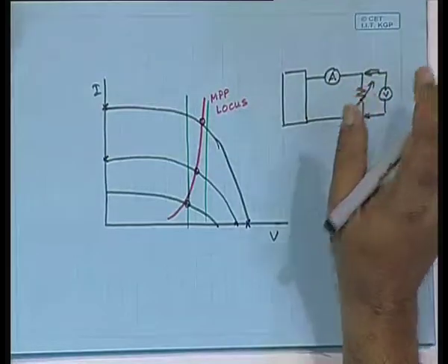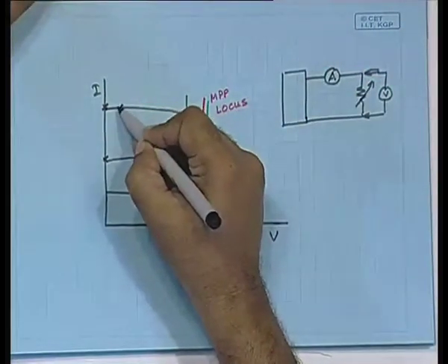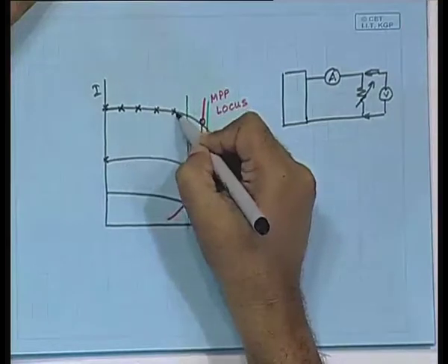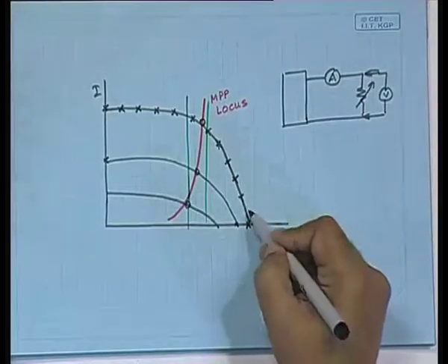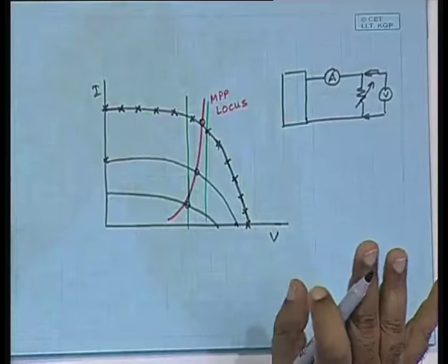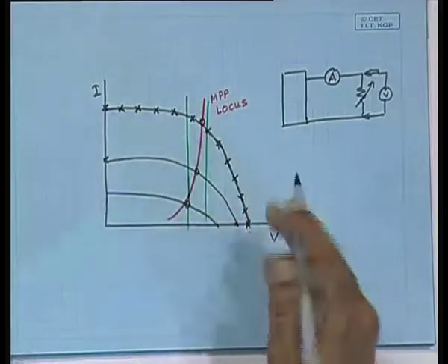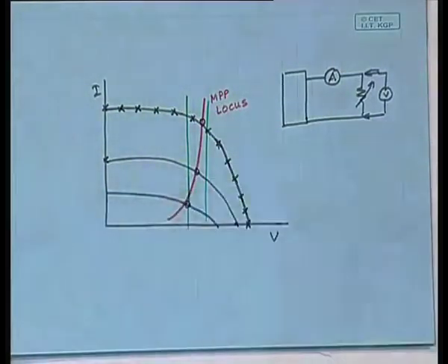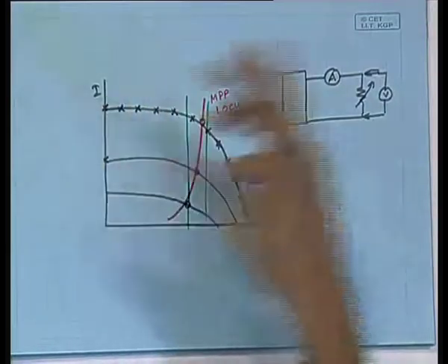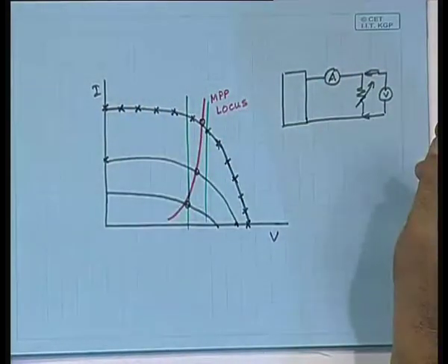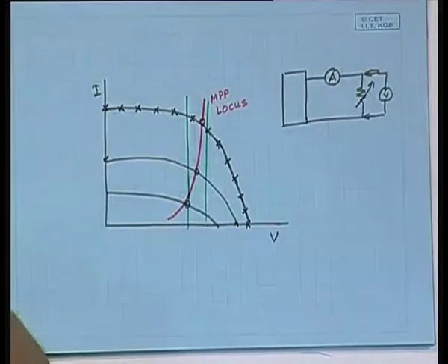Clear? And moreover, in an experiment it is normally desirable to have points located equally distant, right. You would like to do it like this. So, if you do it like this, then you know that okay, I am fine. But it is somewhat difficult to obtain equally spaced points, because what do you normally do? You normally take a rheostat and move it equally and keep on taking readings. If you do that, you will find that they are not coming equally spaced, because the positions are not linearly dependent on the resistance you take.